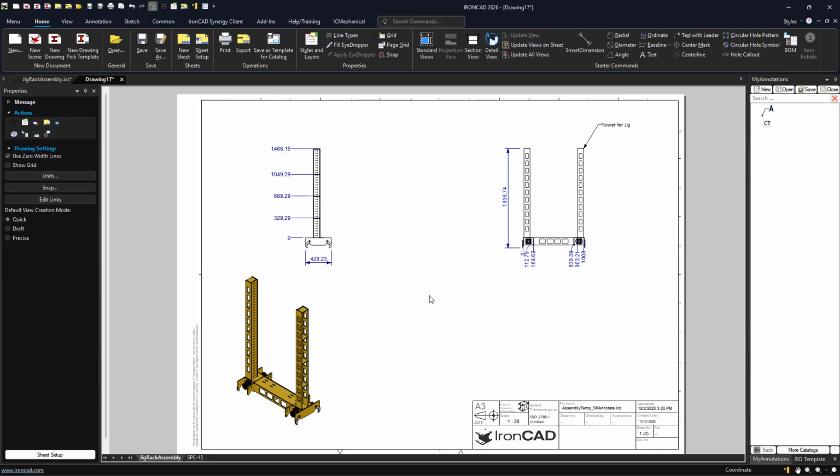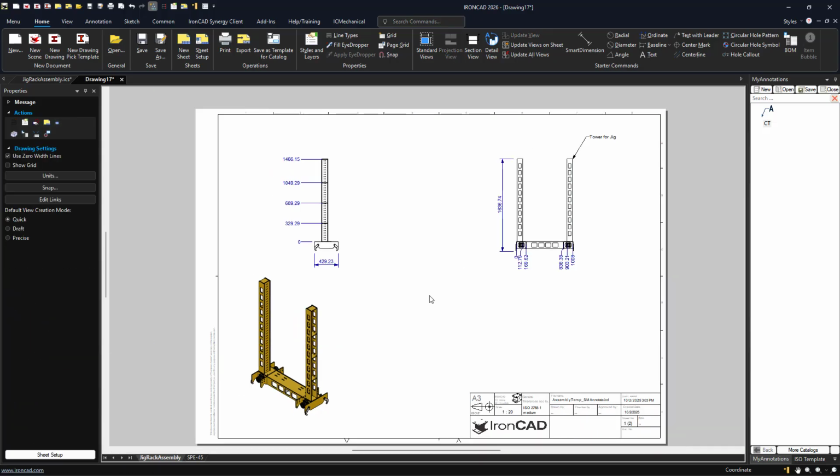So once you set your templates up for your various part designs, whether you're doing sheet metal flat drawings, plate parts, or different types of fabricated or manufactured parts, you can set up your drawings and your assembly drawings very specifically on how you want things to be laid out, and then you save your templates. You now use your process in your 3D to build these annotations. You can reuse this in a very quick way to get yourself pretty close to a manufacturable drawing.